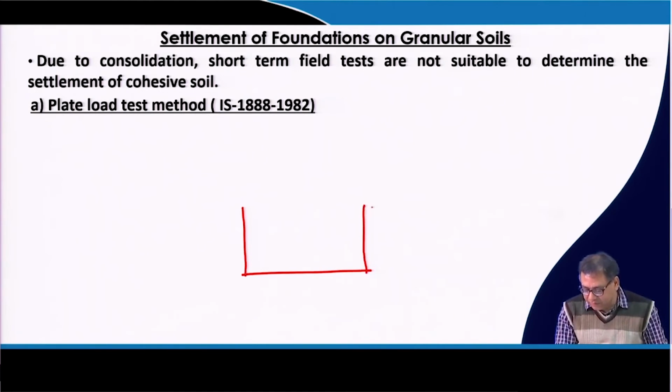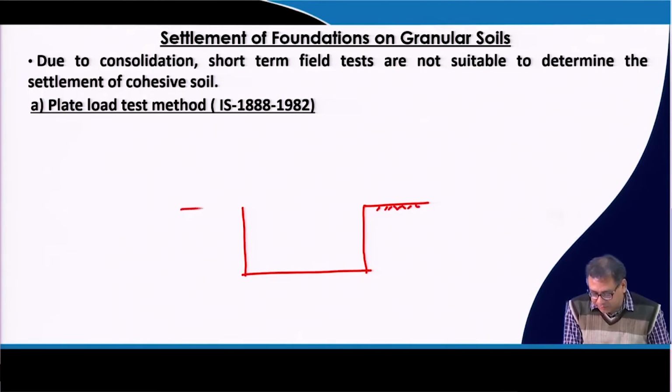In depth we have to conduct the plate load test, and the depth should be equal to the depth of the foundation. Okay.